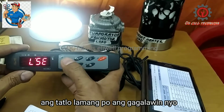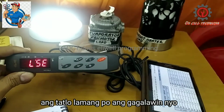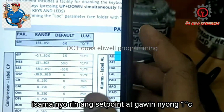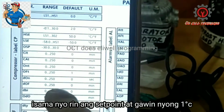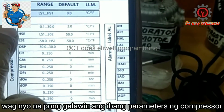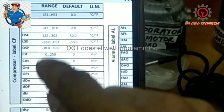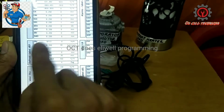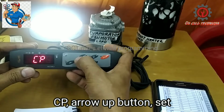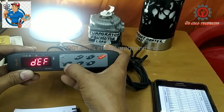Okay, we're going to escape this compressor. I don't want to discuss all about this one. Just change the value of differential, LSE and HSE. That's all. Do not touch this. To the defrost folder, CP here, defrost, and press set.